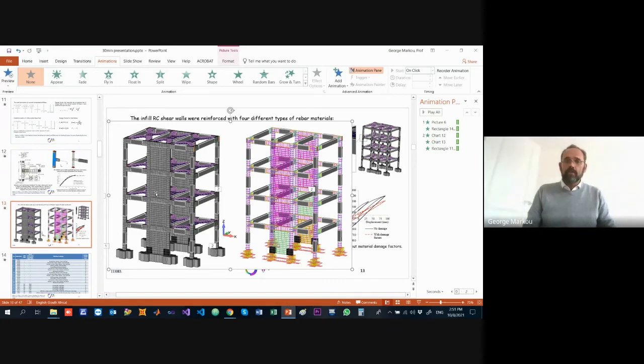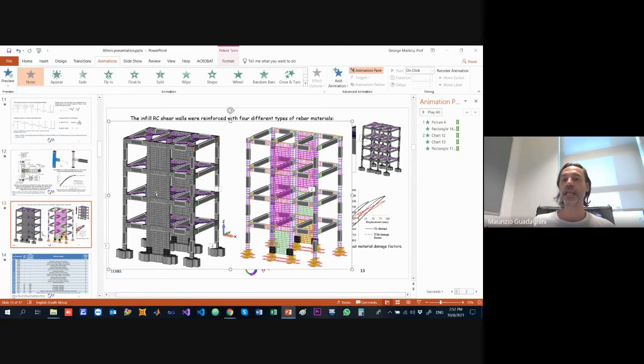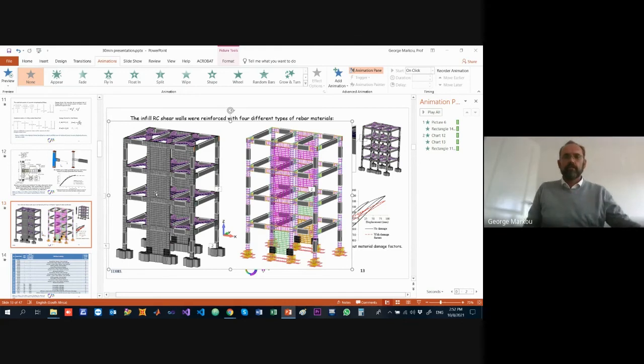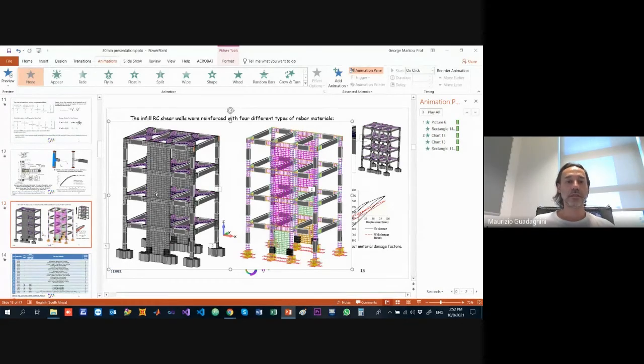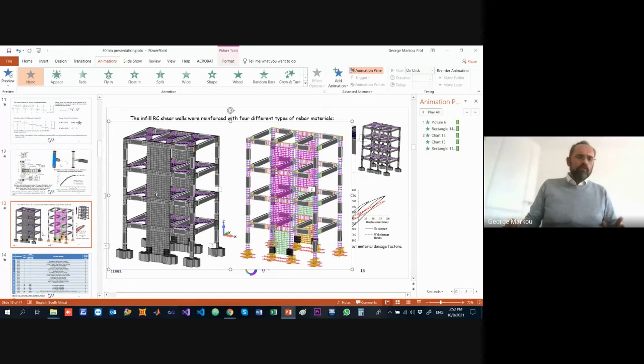And then we got the same numerical model, and we converted the material properties of the embedded rebars from steel to carbon, glass, and aramid materials. And so everything was done numerically. Yeah, and you were using the same area, or were you using? Okay. So you were just replacing the area of steel with an area of reinforcement, depending on the properties. Bravo! And we also calculated the actual cost if we had used that material.